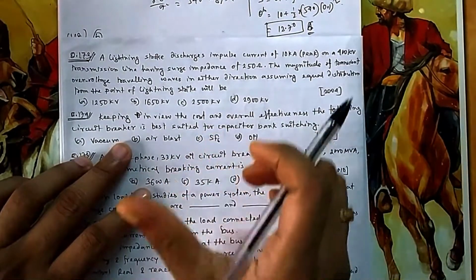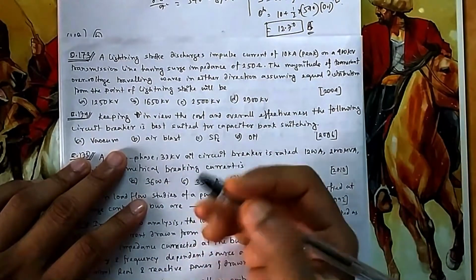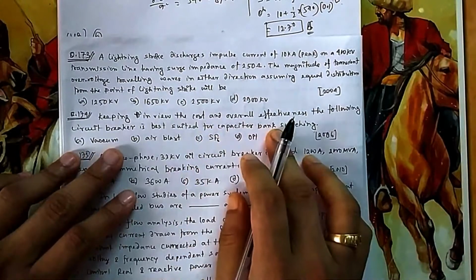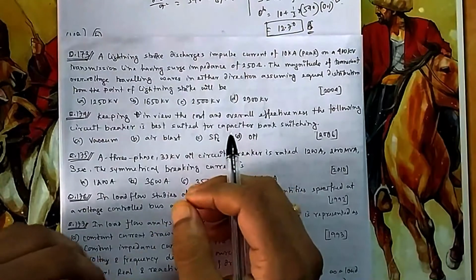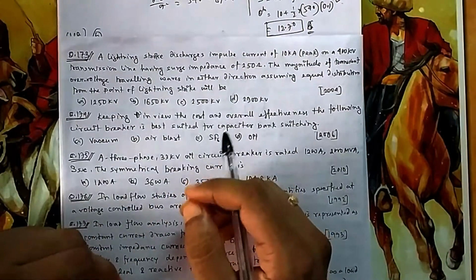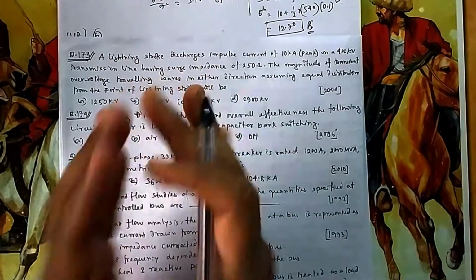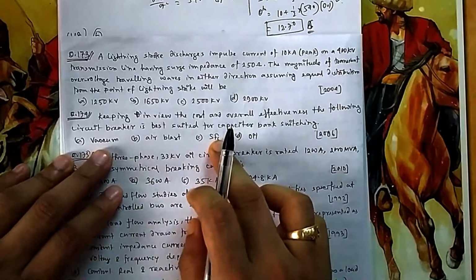Series directly compensates the reactance, which increases the power transfer capability, and shunt is basically to give voltage support. For this type of capacitor bank switching you need fast operation, so you will be using a circuit breaker which operates very fast, or where the dielectric forms between the spacings very fast. That is either vacuum or SF6.